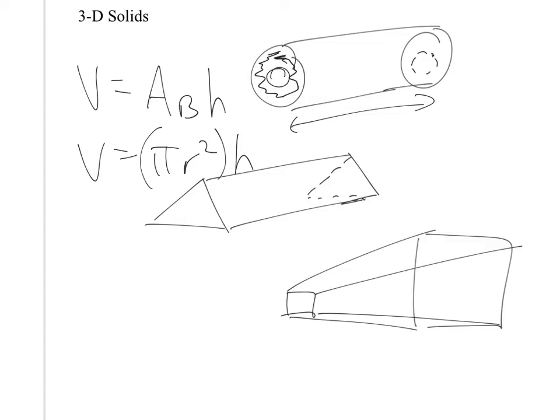That's why if you look at these radiators over here, look at all the surface area. Notice this isn't one block of metal. There's hot water running, not now, there's hot water running through the pipes. All this surface area is what radiates heat. Via convection, really, actually. It's called a radiator. Technically, I would call it a convector. It does involve radiation, but mainly it's airflow over the actual radiator that causes convective currents in the room. And those convective currents cycle in the room.